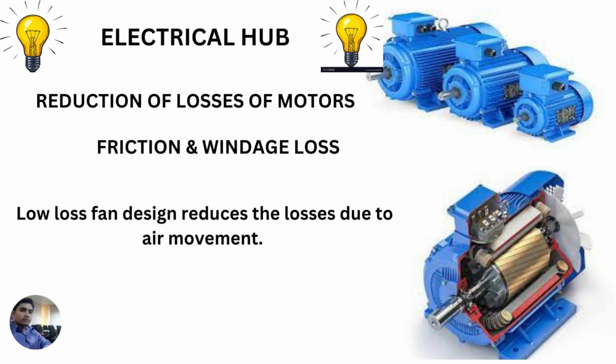So, if the motor is designed for energy efficiency, then the fan would also get smaller, and thus the friction and windage loss due to the fan and the bearing will also reduce.